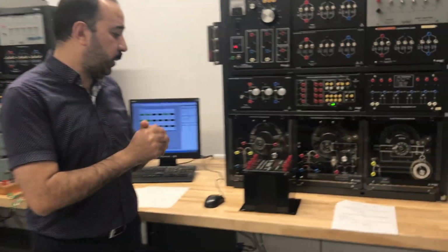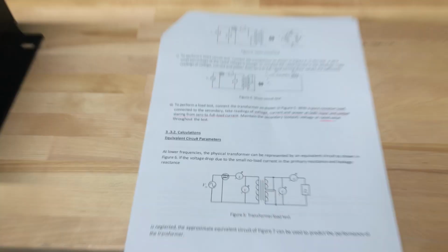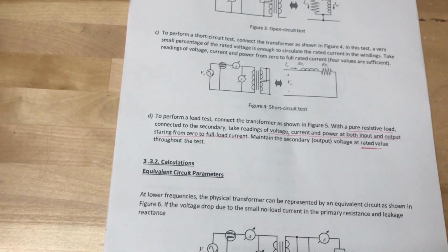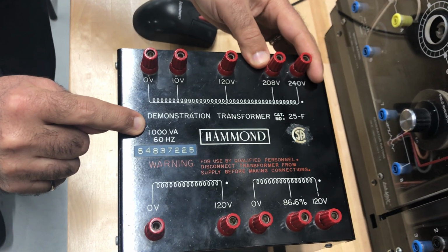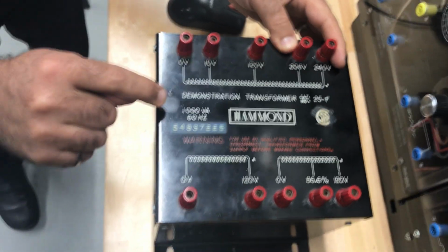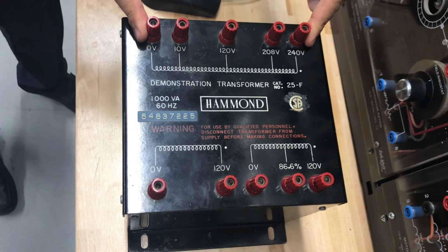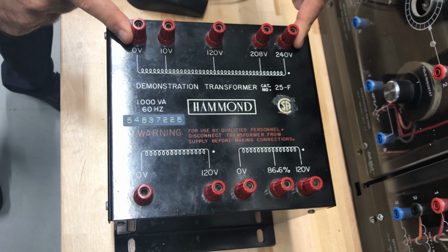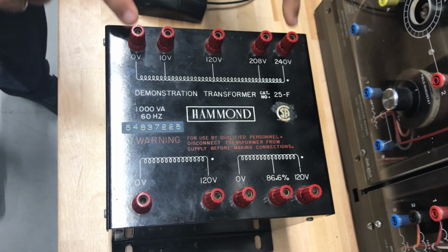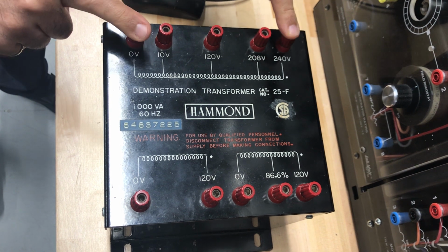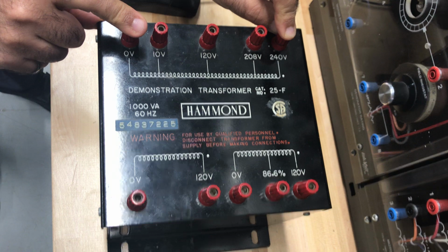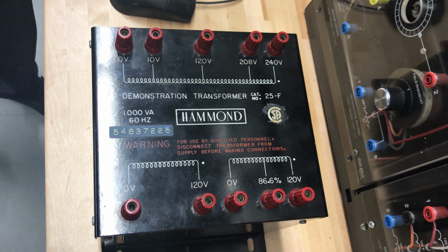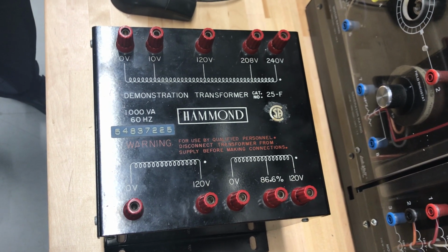Let us start by talking about the DC test. But please pay your attention for the DC test because of the transformer full load power. It is 1000 volt-ampere and the primary voltage is 240. So if we're talking about DC, we are applying DC. Please pay your attention that the current will be very small because you don't have X, you have only resistance.